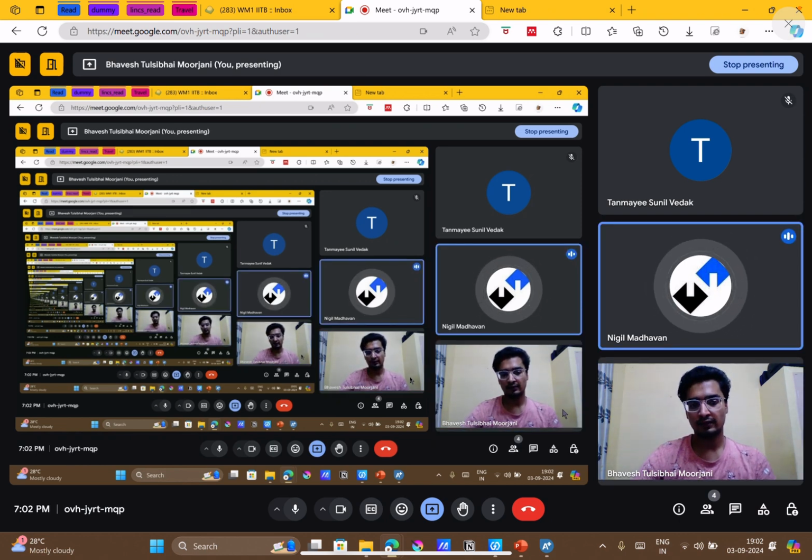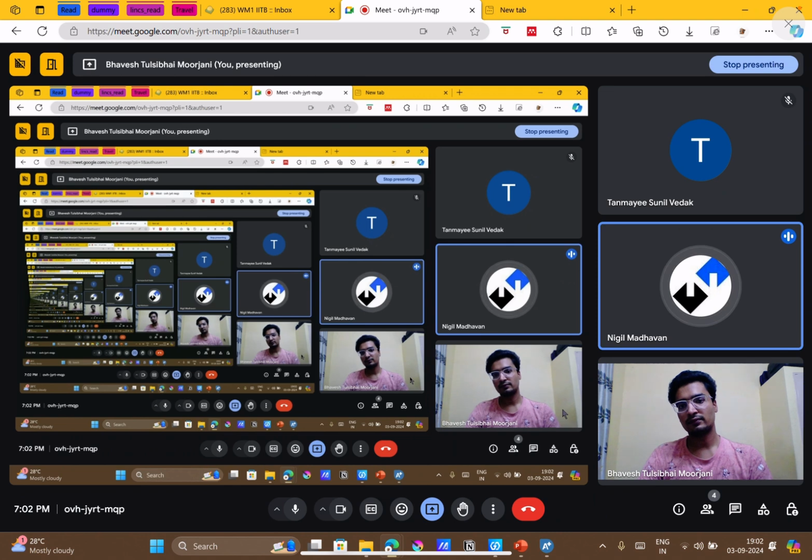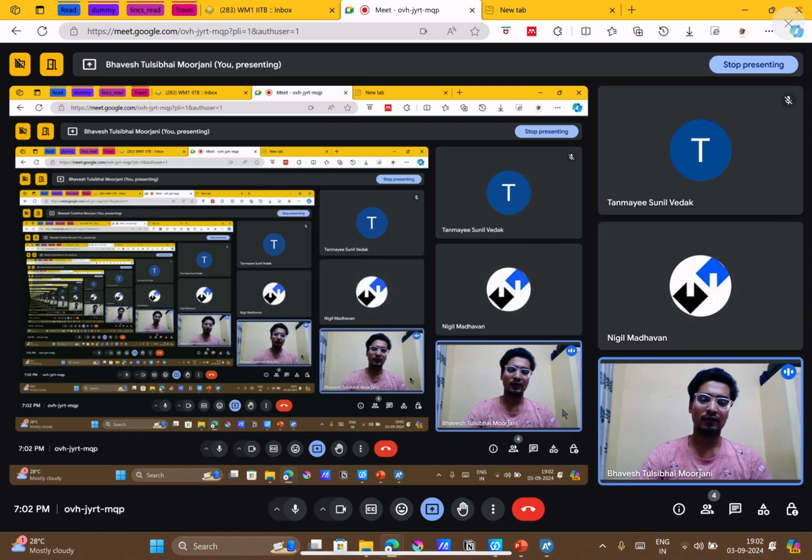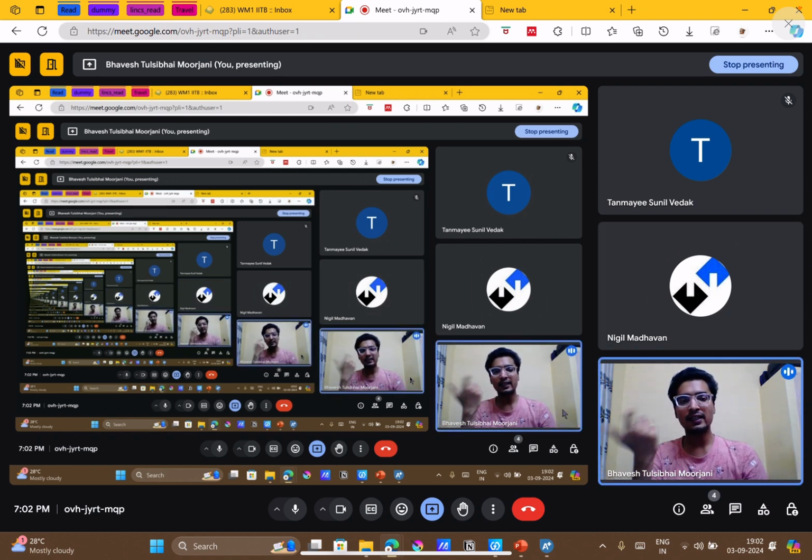For any particular condition, if UNIFAC is the best suited method, then you can move forward with it if you find that the UNIFAC parameters give a better result matching your experimental trends. Or you can further modify it; you can also do the regression of parameters. At the end it comes down to what level of accuracy you want to achieve in your simulation.